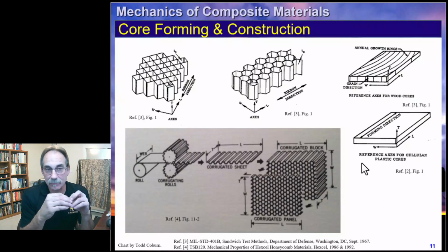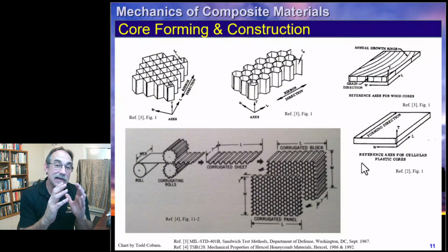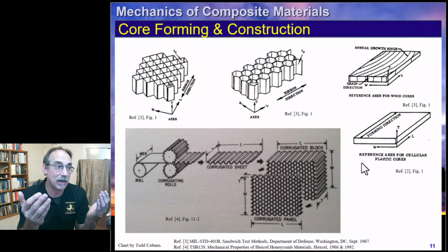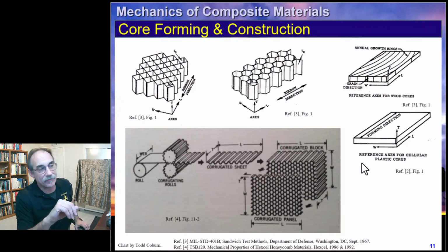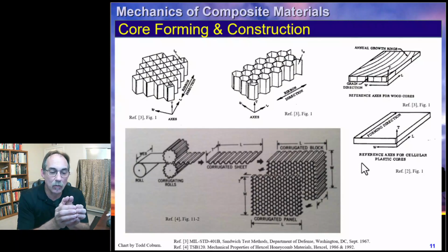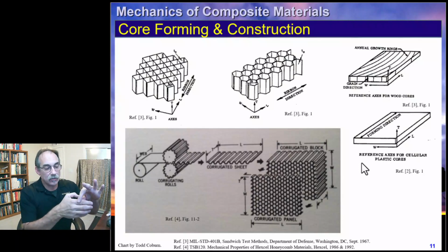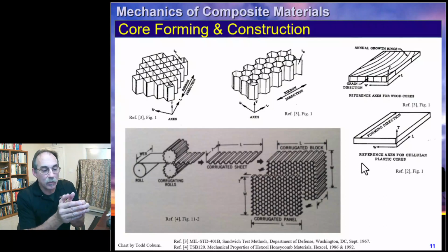And some folks have proprietary methods for welding some of these things together for higher strength applications, or excuse me, higher temperature applications. There are a number of different proprietary methods for that. But basically, the basic idea is we have a core. When we're all done and we've expanded that, even though each little foil is extremely thin, when it acts together as a whole and is bound in between the face sheets so it can't move too much relatively, it has pretty good shear stiffness in both directions, although the two directions will often have different properties, both in terms of modulus and strength.